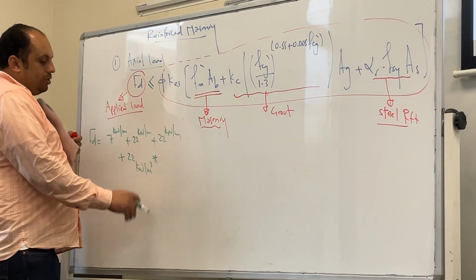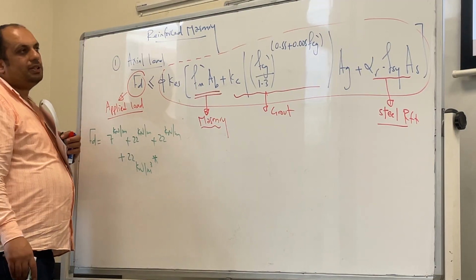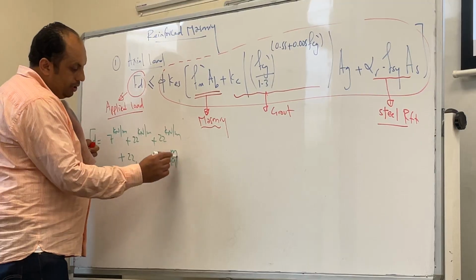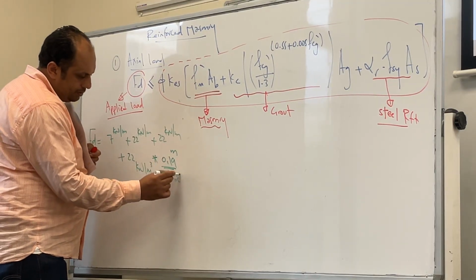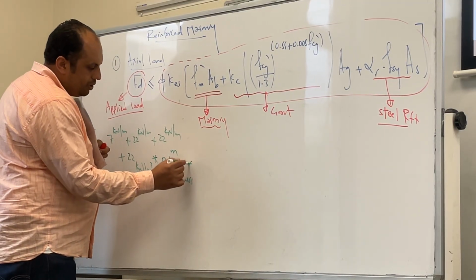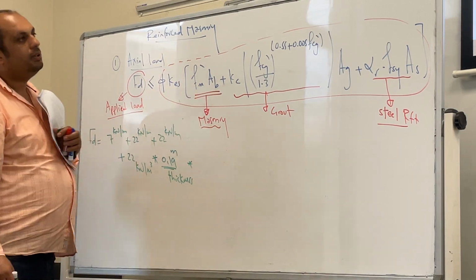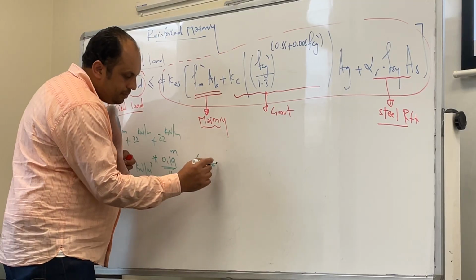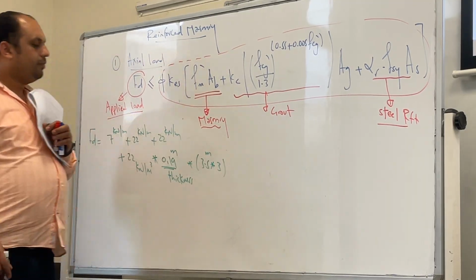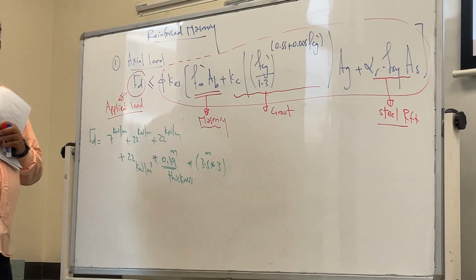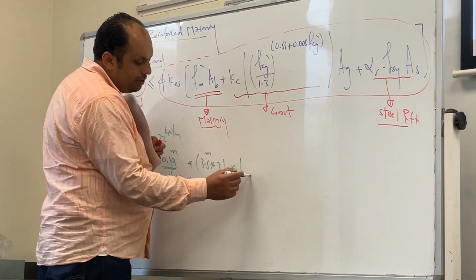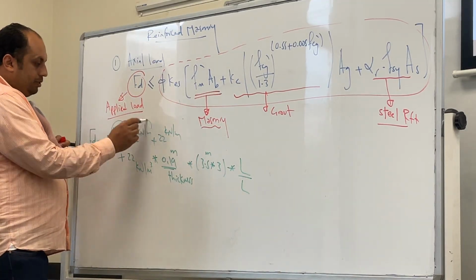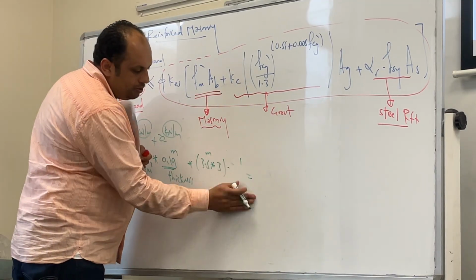So the cross section: the height times the thickness. What is the thickness? 190, so 0.19. Times the height. How much is the height? 10.5, 3.5 times 3 stories, each story is 3.5. If you want the volume, I need to multiply by L, then divide by L to get it as uniform load, because all the loads are distributed loads, so we need to distribute again.